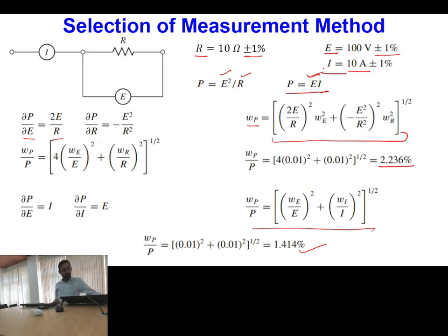So what are the things we need to follow in the planning of the experiment, that I will show you in the subsequent discussion. But this is important: uncertainty analysis is something that, whenever you are presenting the results, you have to mention how much uncertainty is there in your results. But uncertainty analysis, before deciding the instruments for your experimental setup, you have to perform this, and then based on that you have to choose the methods of measurement.